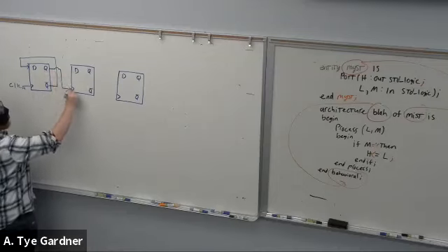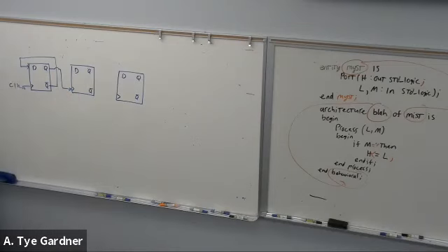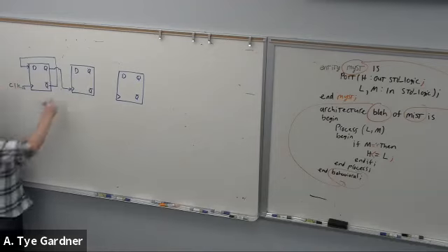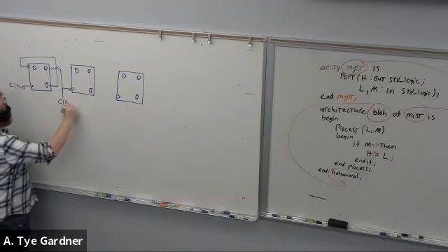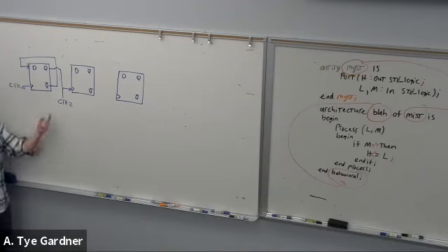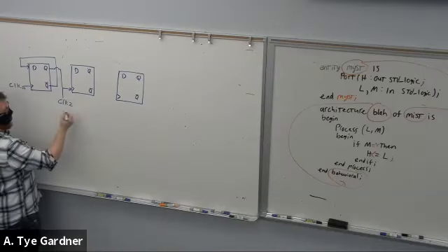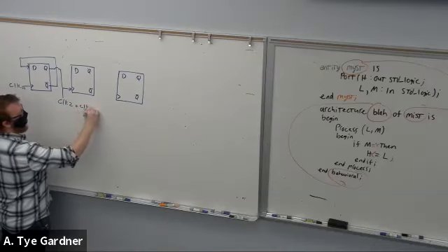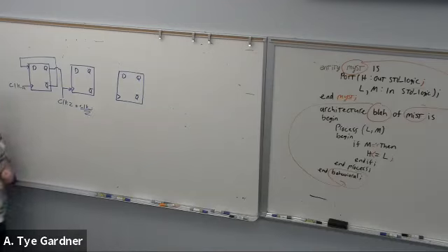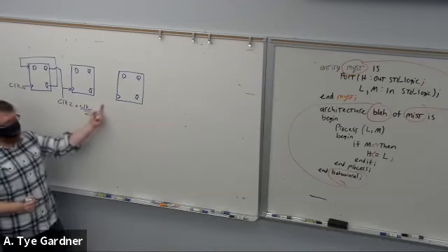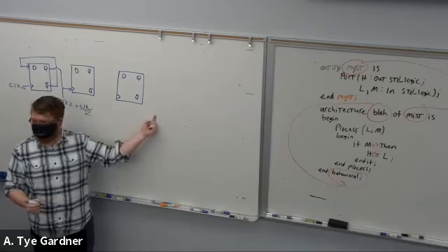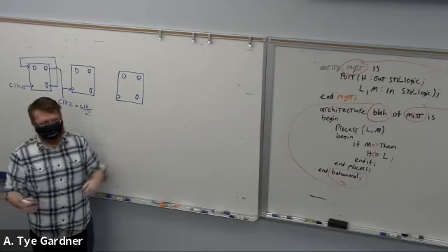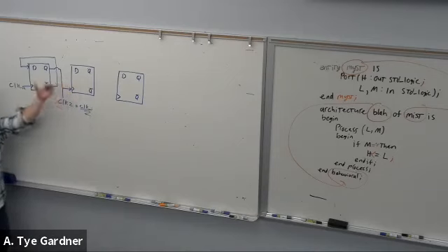Yes, exactly. That makes it asynchronous. And then you kind of rinse and repeat. Exactly. And so if I call this clock 2, what is the speed of clock 2 relative to clock in? 2. Yeah, exactly. So clock 2 is equal to clock in divided by 2. Right, so divide by 2, repeat, divide by 4, repeat, divide by 8. We didn't do a lot of homework on it, but it's directly out of your notes, so I wouldn't feel too bad asking that question.